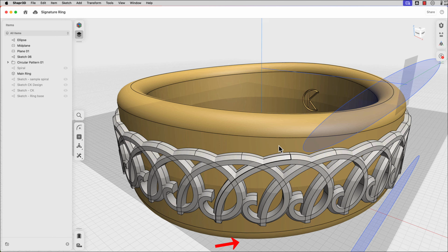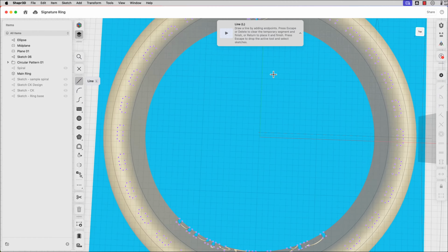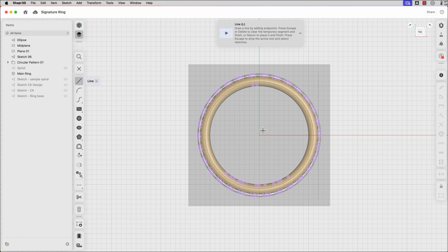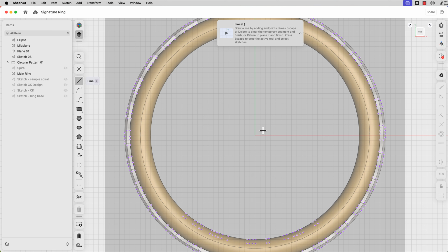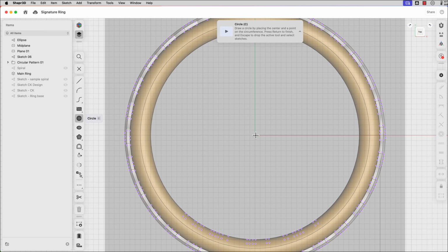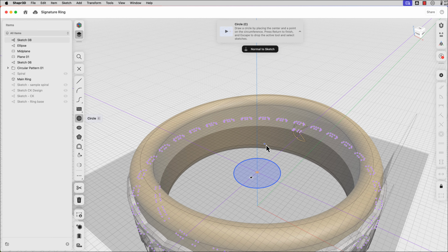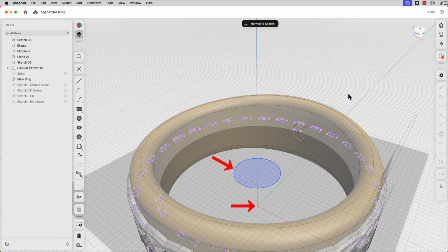First, let's use this midplane that we already have in our model. Hover over it and press the spacebar to make it the active sketch plane. Now this is a sneaky little trick because now I can select the origin as the center point for this circle. Let's make it 5mm. The reason why that's sneaky is because we were actually using the apparent origin. That is, we were right above it and actually sketched the circle onto the midplane and not the plane that the origin is actually on.